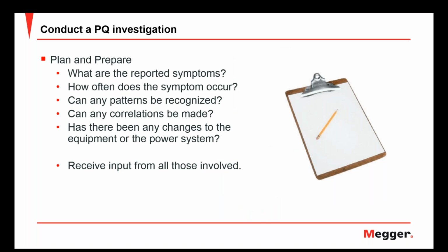So when we want to do a study, we want to troubleshoot something, how do we want to go about this? The very first thing to do before hooking up anything or taking any measurements is first plan and prepare. First thing we have to ask is, what are the reported symptoms? How often do these symptoms occur?